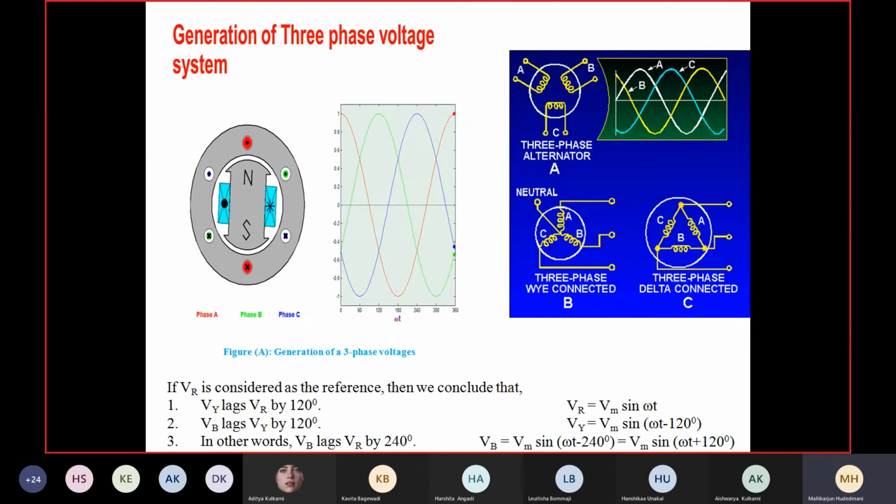When I have a 4-wire or 3-wire system, again it becomes necessary to understand the distinction of phase voltage, line voltage, phase current, line current, like that. For that, basically we require to understand how the three-phase system is interconnected. It is interconnected either as a star or as a delta. That is the first thing we should notice. Then I will find leads here. This we will study in another derivation itself. Meantime, 3 leads are there.